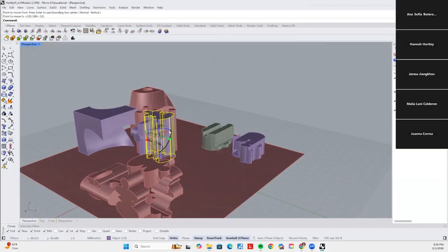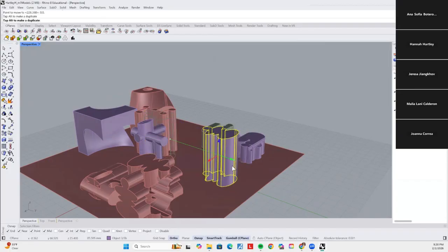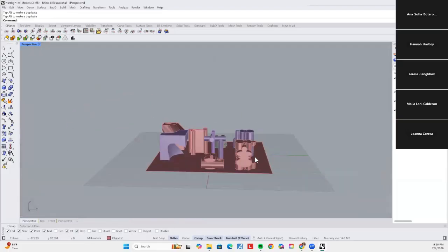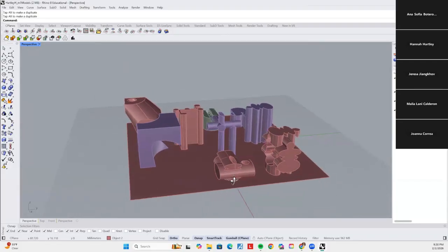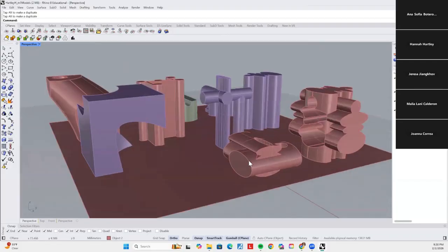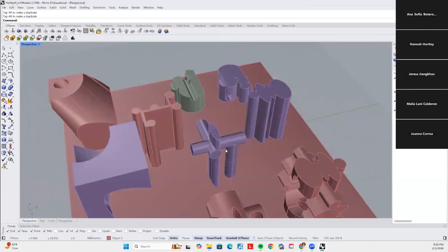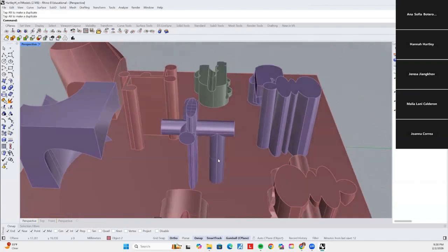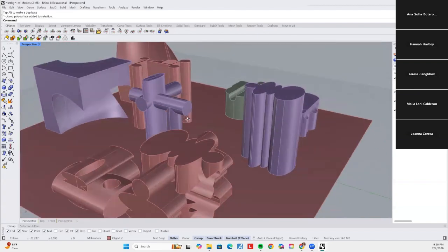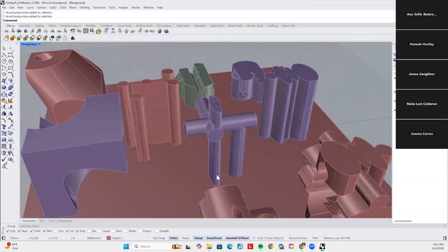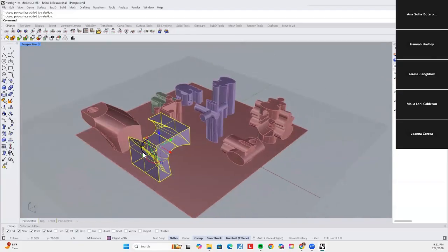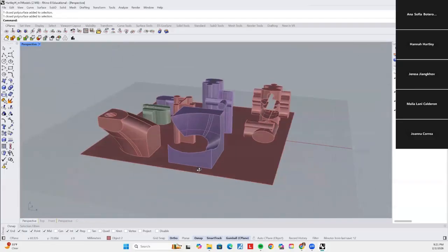So you want to make sure when you're setting it up, you create it on the flattest side, because I'm just the one printing it. I don't know what you want it to look like, or which side you want to look the prettiest, the side to look the best. So it's important. And for this one, how it is, it's good, because there's only one leg, but here we have two legs on this face. So that one's better. And then this one, I would try flipping it 180. And yeah, that looks better to me.